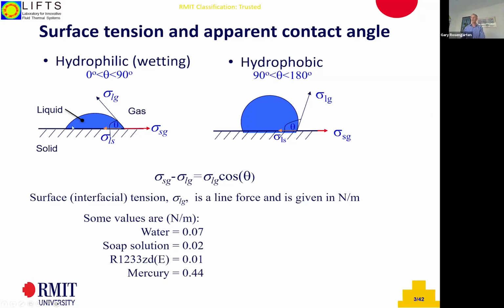And of course, the other property that is very important in two liquid or two fluid interfacial systems is the surface tension. Everything from water is the highest liquid, apart from liquid metals. If you're on really, really high surface tension, go to liquid metals, great heat transfer fluids, but maybe not great to use in large scales. And if you want a dielectric fluid, useful in some applications, but you've got to realise that the interfacial tension is much smaller than other traditional liquids.